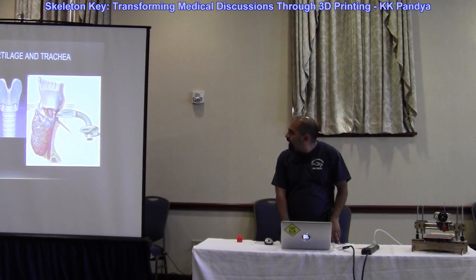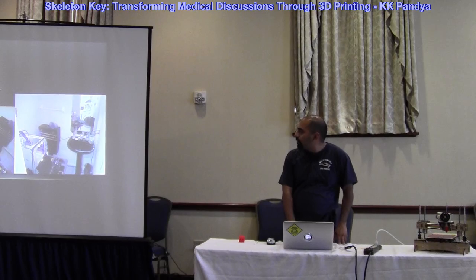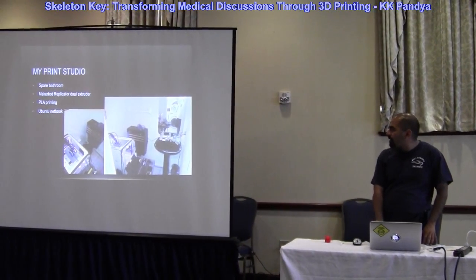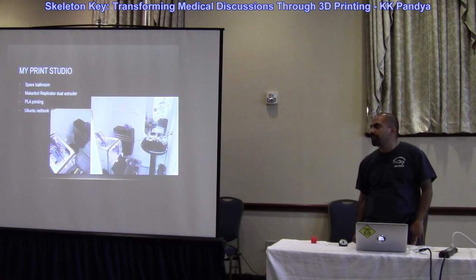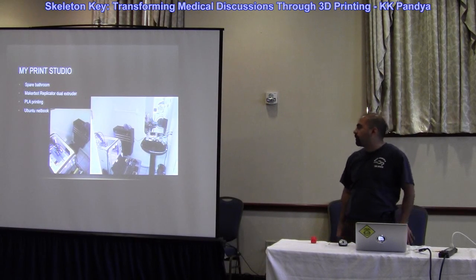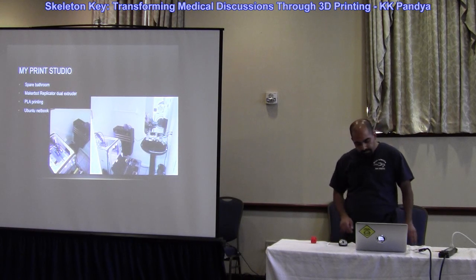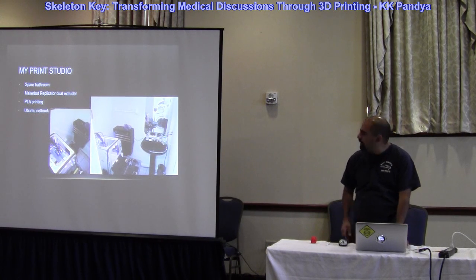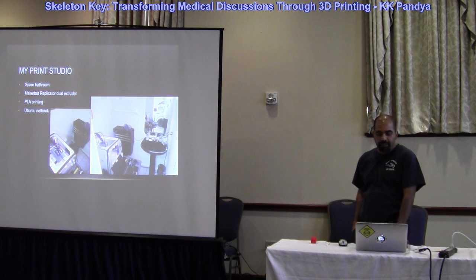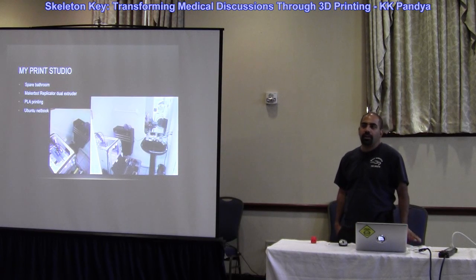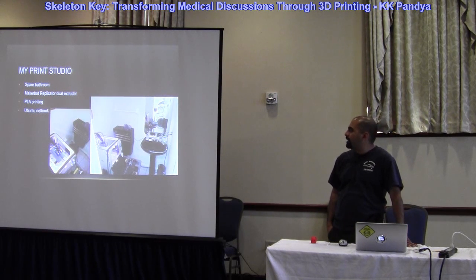So briefly, as far as my 3D printing setup, I've got stuff set up in a spare bathroom right now. It's maybe a 6x8 room with the printer on a rolling cart. And it's been working. The main issue I had was isolating for temperature and isolating for vibration. So just advice to anyone else getting into 3D printing, I've had the best results with isolating as much as I can.